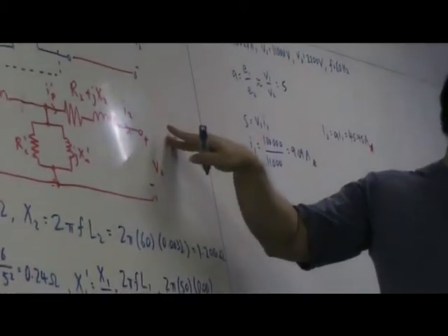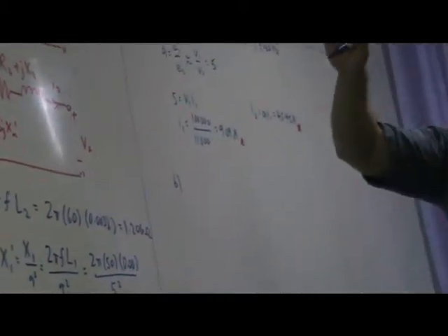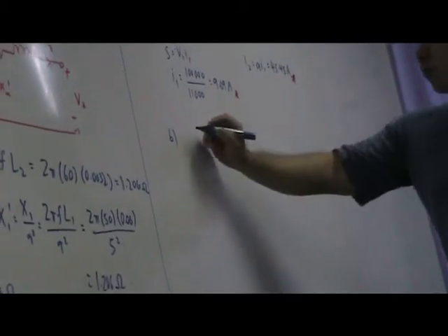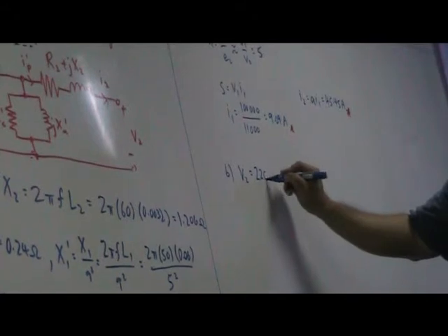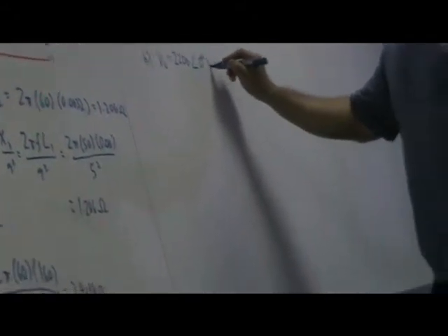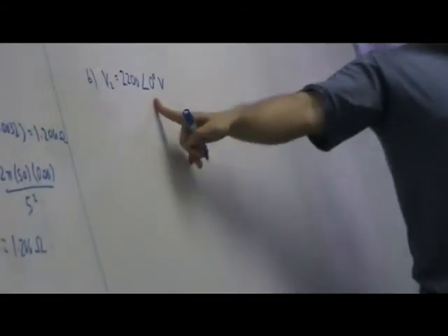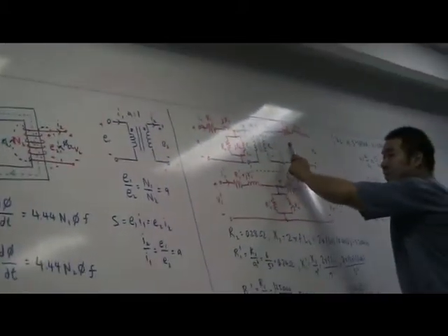It's an AC circuit, so everything is AC. So you have to use your phasors to do it. So V2 is... I put 0 as the reference. 0 just means it's the reference. We want to find V1. So we find V1 on this circuit, or V1 prime on this circuit.